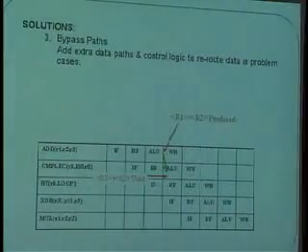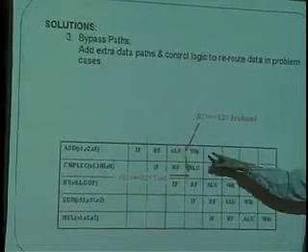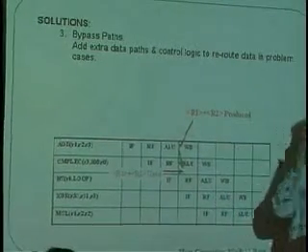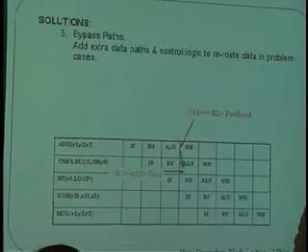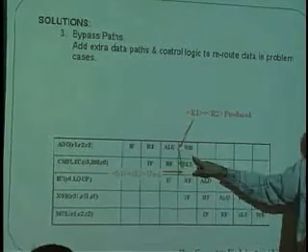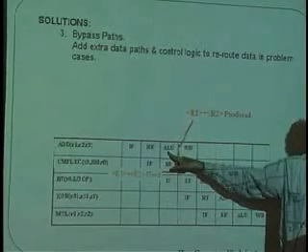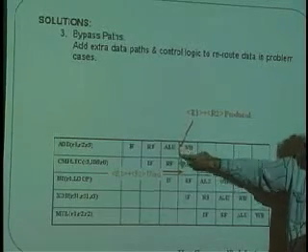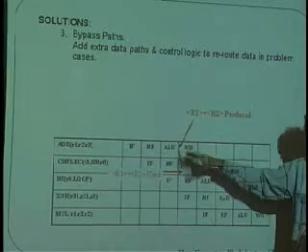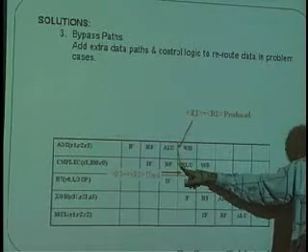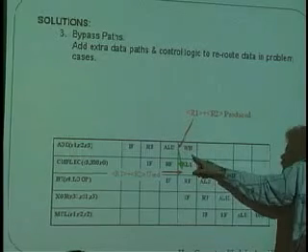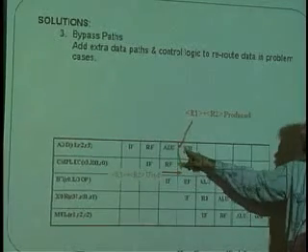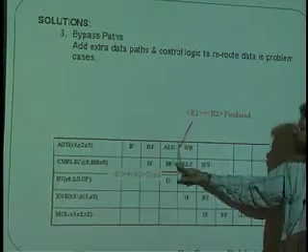And it's realizing that even though if I write the result R3 over here and I try to fetch it over here, then I'm sort of messed up. The truth of the matter is, and this just happens to be true, and it's nice, that I've computed what I'm going to write, not in this stage, but in this stage here. Here's where the ALU figured out what the sum of R1 plus R2 was, right at the end on this edge. And here is where this ALU, independent of anything else, needed to know what R3 was. Now, R3 didn't get a chance to be stored, and we didn't get a chance to read it, but the data did exist in the machine somewhere, about to be written, after we had tried to read it, but we hadn't used it yet.